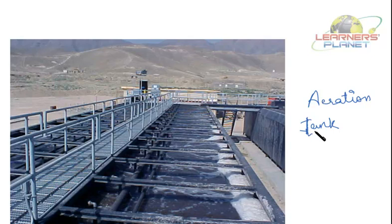Right? So in the aeration tank or in secondary biological treatment, it removes the dissolved organic matter that escapes primary treatment, and this is achieved by microbes which consume the organic matter as food and convert it to carbon dioxide, water and energy for their own growth and reproduction.